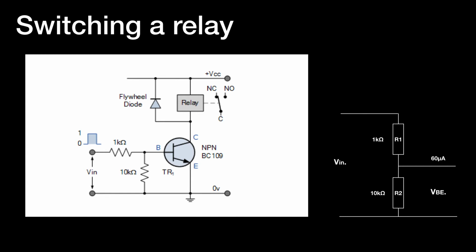then a reasonable impedance, or resistance, would be presented to that signal of the order of 11 kilo ohms, slightly shunted by the base emitter, because remember 60 microamps or so might flow into the base, but a reasonable impedance so as not to affect the signal source, and the relay would pulse in time with the signal coming in on the input.